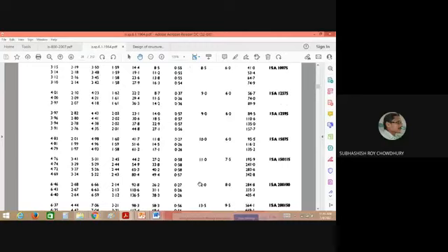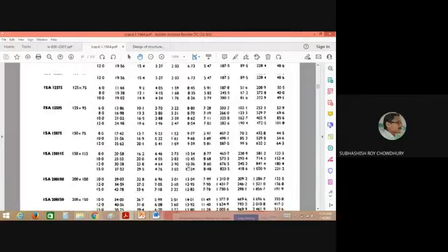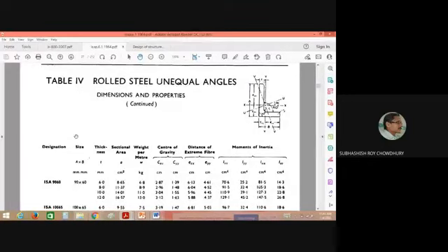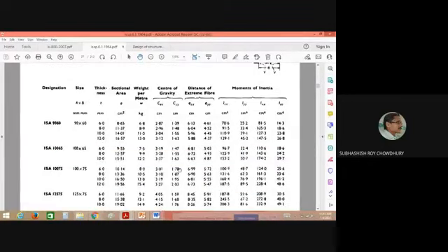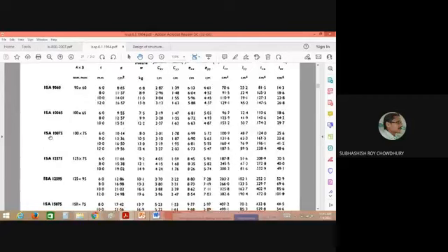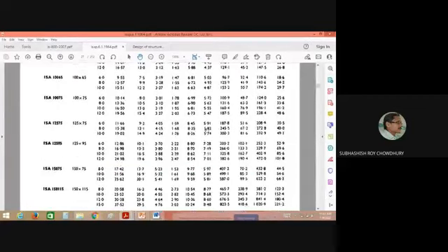In my part, I will tell you the procedure of designing of the beams and columns. There I will suggest you to use the ISMB sections in case of I section. In case of channel section, ISMC sections. If you want to use the angle sections, because there is no such variation, only ISS sections are there. So any ISS section you may use.